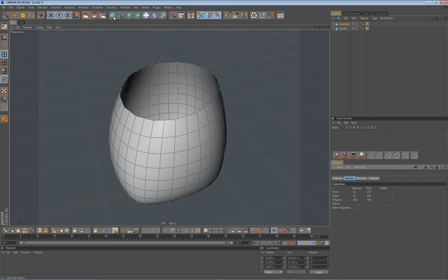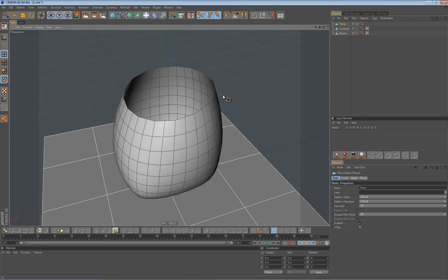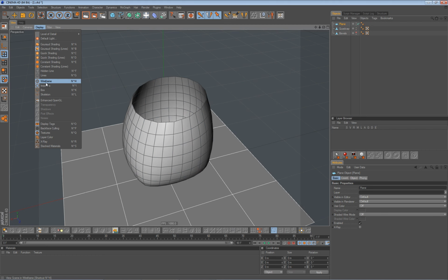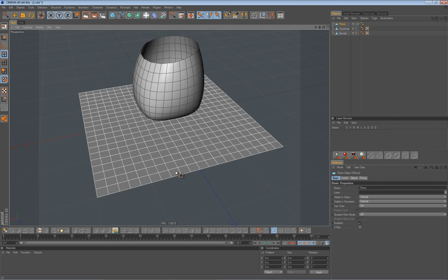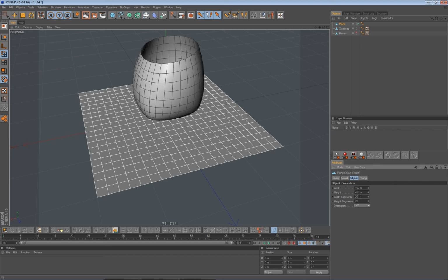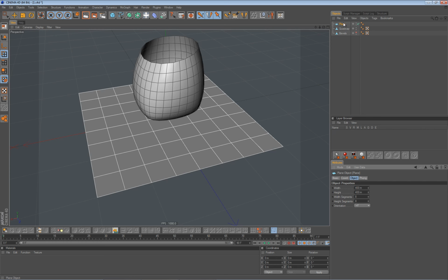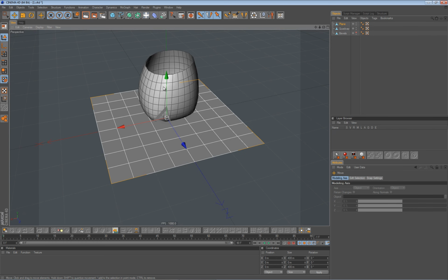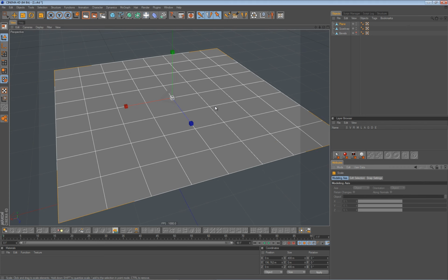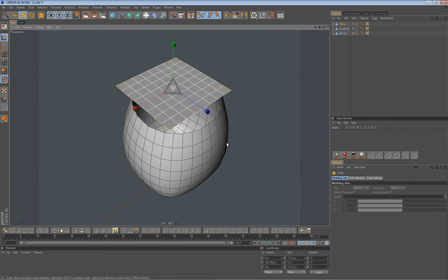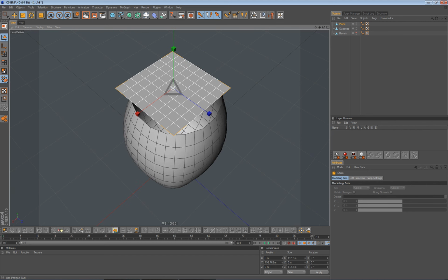So what we want to do is create a plane, and because a plane has 4 sides, you simply divide that 32. Go here to wireframe mode to exactly see the amount of information I have. So if you divide 32 by 4, you will get 8. So we'll drop 8 here in the segments and simply convert that.